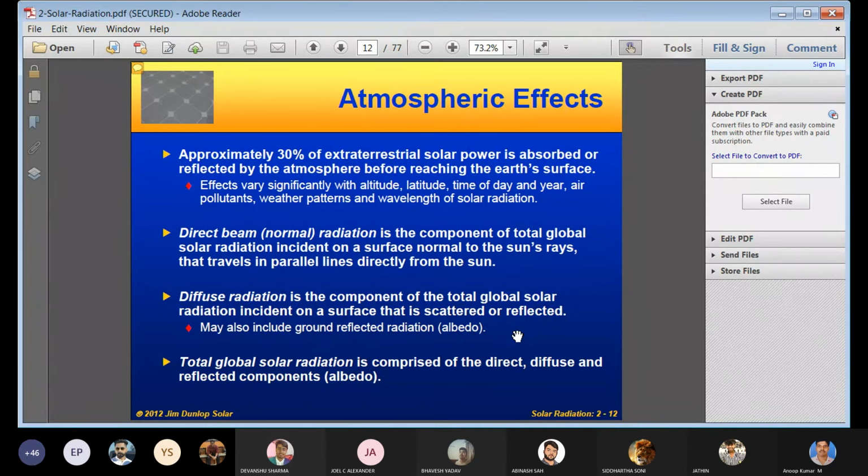Total radiation on Earth's surface can typically be 700 to 900 watts per square meter on a sunny day, out of which maybe 70 to 80 percent is direct and 30 percent diffuse, if we are measuring it outside. If it is inside, almost everything will be diffuse only. So you can expect some 300 to 400 watts per square meter in a clear time, noon time, etc.